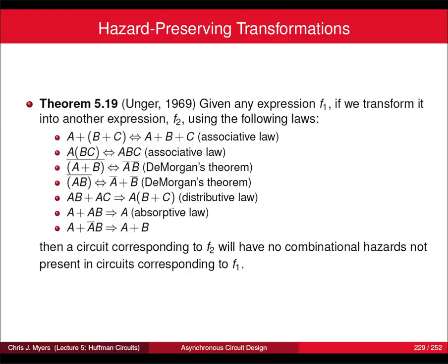That's all good, except an arbitrary multi-level logic synthesis engine sometimes takes backward steps. It's sometimes advantageous to actually add complexity temporarily to your circuit, and then it simplifies more later. So sometimes you might actually want to do something like that. It doesn't seem clear why you would want to do that. But the multi-level synthesis engines are going along your landscape, climbing hills sometimes by adding a little complexity that then helps to simplify something else out along the way.